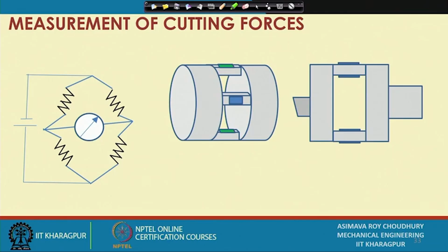Naturally, with some known force values we have to calibrate the machine so that we understand which particular change in resistance stands for what particular force. Now, how do we measure this change in resistance and utilize it for our values? Use of a single strain gauge won't register a marked change. So, for that we can employ a number of such strain gauges.